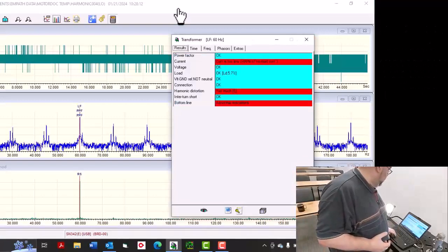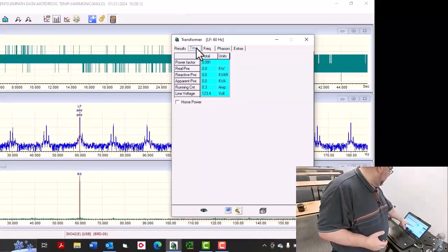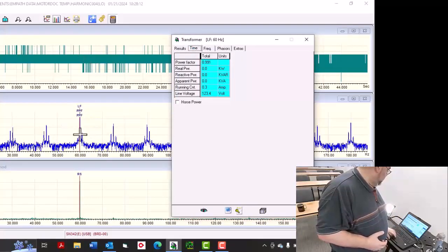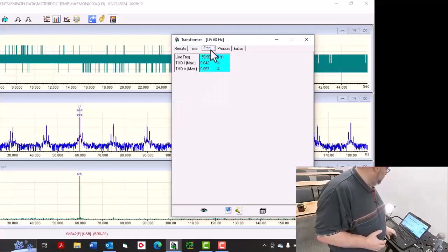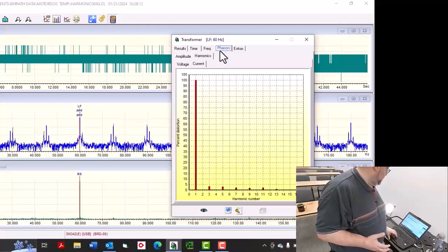Okay, so both on there. Now the side bands that are occurring here, down here, those pop up with the LED. Those have to do with the harmonic content. So we're at 0.991. Okay, so not too bad. We have high harmonics, about 6.6% current, and actually really close to 1% in voltage.